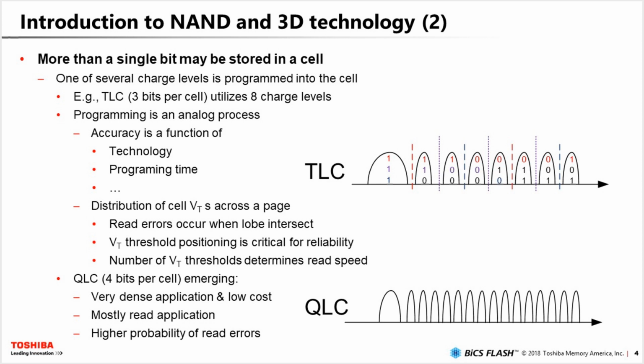And the number of trials you try to read a NAND cell also determines the performance. If you try to add additional reads, it will cost you in performance and time. So there's a trade-off between reliability, programming speed, and read speeds.